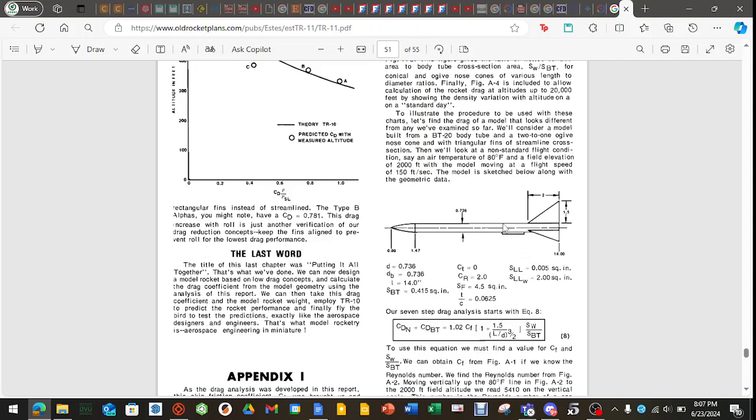No, because they're both CFD in a way. OpenRocket calculates all those things and also tells me the apogee and the ejection charge timing, if I'm going to put in my own gunpowder for a disposable motor, what time to set that for. There are things that OpenRocket does that CFD does not do, and vice versa. What CFD does that OpenRocket doesn't is mostly visuals. It's really hard in OpenRocket to visualize what's going on with drag, but you can do that with CFD.